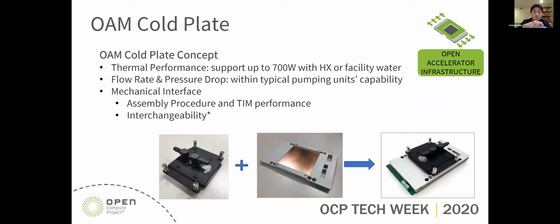If you look at how the cold plate is mounted into the OEM products, you're adding the cold plate itself to the spreader plate and then to the OEM product. By doing it this way, you are absorbing all the power or heat generation of the components on the OEM PCB into the spreader plate, and it will be taken away by the cold plate.